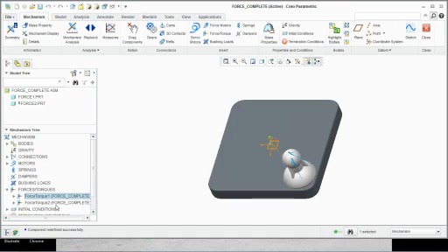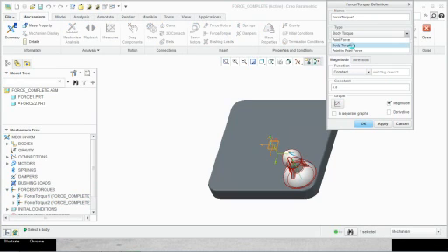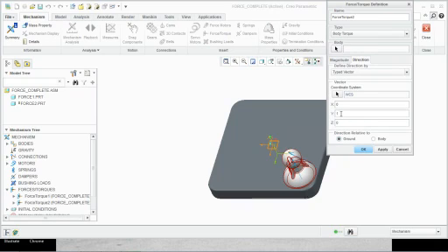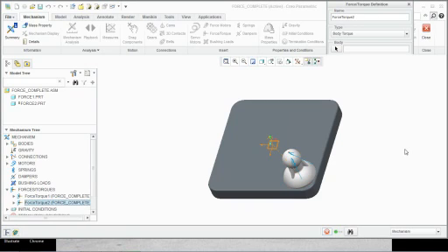Next force is body torque. Notice I used point force earlier, now I'm using body torque. Alright? So in a body torque, I'm saying again it's a constant, that's the value, and y direction is specified. That means it's going to rotate about the y axis. Okay? So let's go ahead and look at the analysis.